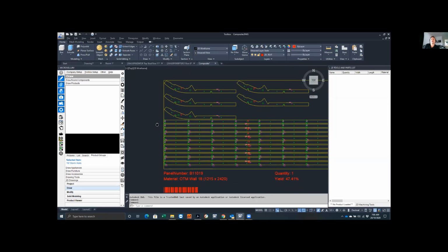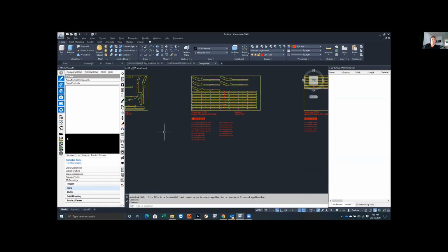Nice. And yeah, all of the wall panels. So it cuts out all the holes for the windows, the doors, everything. What they were doing before was they were cutting it out on the CNC, but they were doing part by part processing. So every single part, he was dropping into 2D, drawing every single route on that, and getting a lot of mistakes where window positions or hatches were in the wrong location. Now it's all done from the builder, and he gets all of that in the right spot every time.